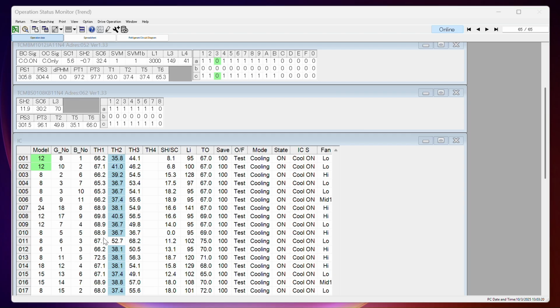Okay, as we can see, this device lost refrigerant. But notice this. I've got 2 devices on port 3. Well, you can actually have multiple fan coils on one port, but what's going on here is the sub-branch controller. When you have a sub-branch controller, the important thing to note is what is its address, because the sub-BC needs to be addressed 50 higher than the lowest indoor unit connected to that sub-BC. So all indoor units that are not on the main BC have to be addressed higher than those on the main.